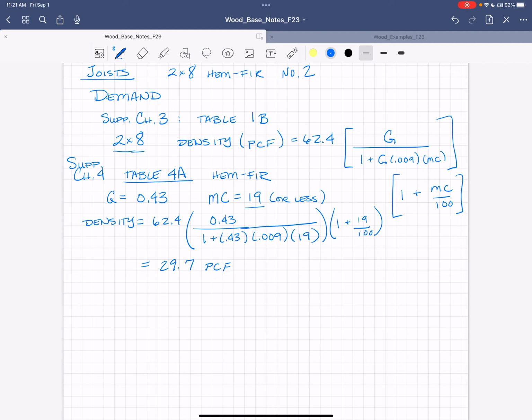All right, I now will go back to table 1B, because it's going to give me the weight I need. And all this is to find the weight. So if it's concrete, it would be 150 pounds per cubic foot times the volume we have, or the area over the unit length. Here, each species is different, so we've got to go look and figure out the density of these species, and then we can figure out the weight.